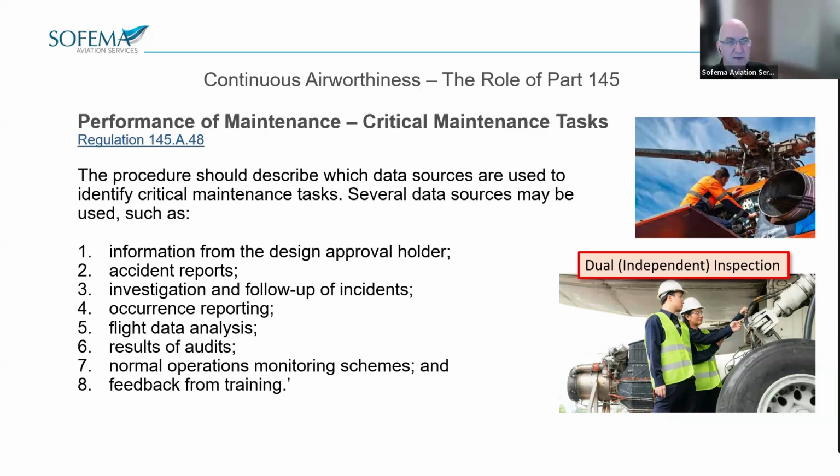So this is where the support staff come in. A licensed engineer can inspect the work performed by the authorised person who is a licensed engineer also. Ultimately, though, the authorised person issues the certificate of release to service. So one engineer goes in, he performs the adjustment and does the work. He inspects it for himself. He's satisfied. He calls in the independent person who performs a second inspection. And when he's happy, the original licensed engineer signs off the certificate of release to service.